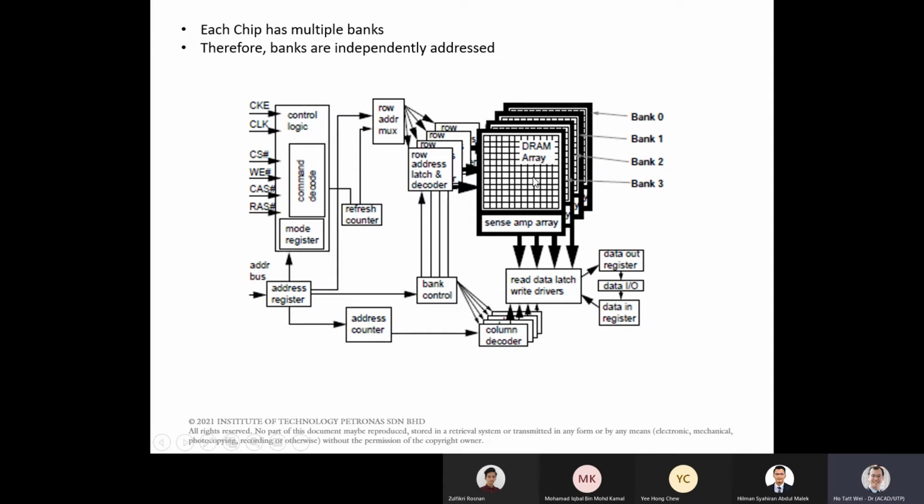So while I'm doing the access, sense, and restore of the first bank, I can start the pre-charge of the second bank, which is using a different address. Okay, so having multiple banks in an SDRAM allows me to pipeline different memory accesses so I can speed up and increase the throughput of my SDRAM. You got me? Is this clear?